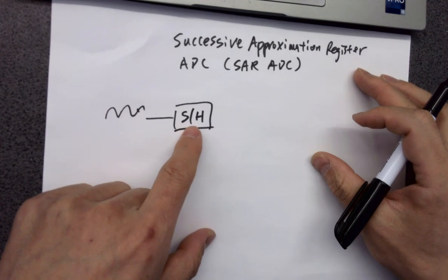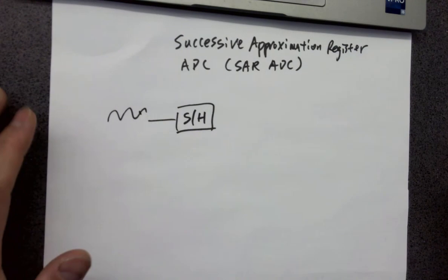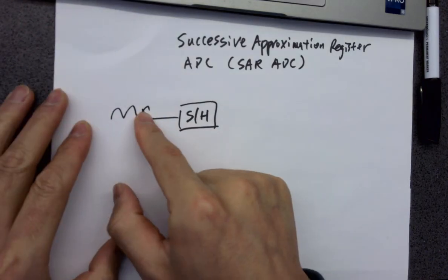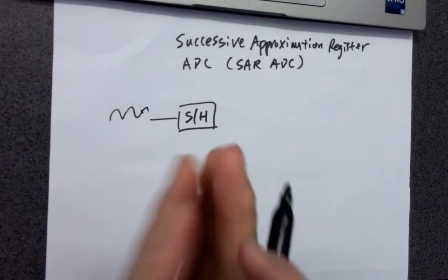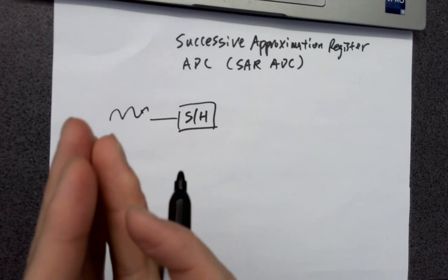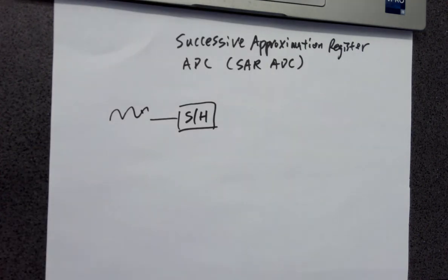It's a lot of things to be covered. But for now, let's just assume that there's a capacitor able to hold it at a certain level. So the input will be captured and held, and then you have the opportunity to do the ADC conversion because the DC voltage is held there for a certain period of time. It's a DC voltage that is not changing. So we are assuming that this input is not changing, but actually it's changing, right?